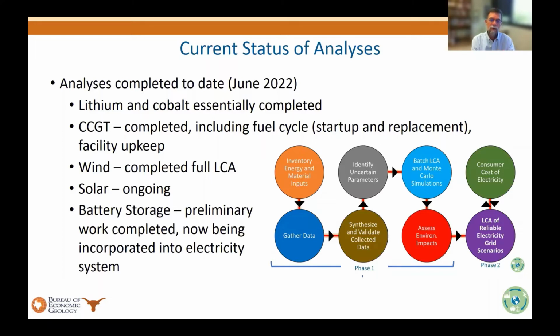We're working with a utility scale battery manufacturer to make sure that when we size the battery, we are adjusting the size of the facility itself. We're dealing with discharge rates of the battery. So how often are the batteries discharged? What are the cycling on and off, and how does that affect the life of the battery? These are all sorts of things that we're doing, and we're solely in the red box right now.